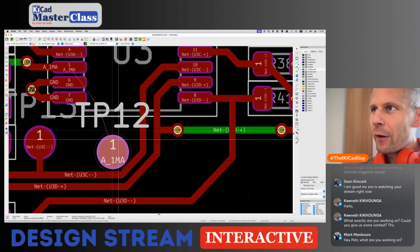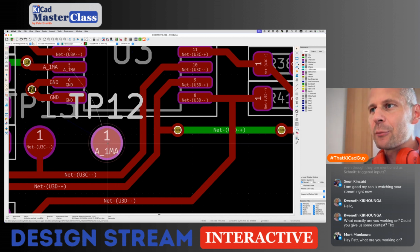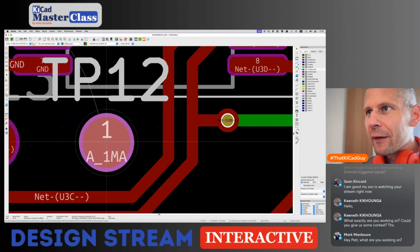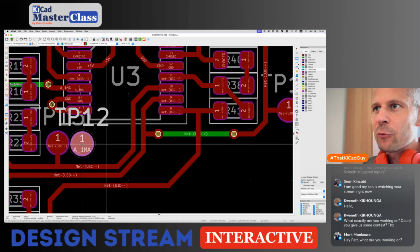Now you can grab anywhere, but the feature in the previous version was that if your cursor was close to the center, it snapped to the center. So you always snapped the footprint at the center, which is very important. Now you don't. So you can only estimate where the center is, then grab the footprint and align with the neighboring footprint if you want to align the footprints.